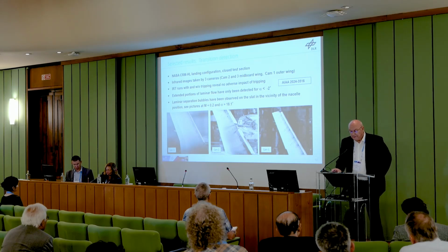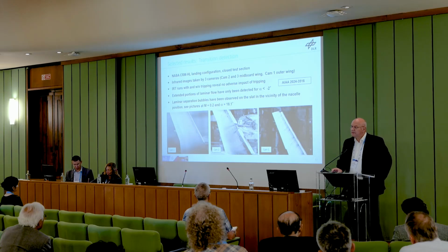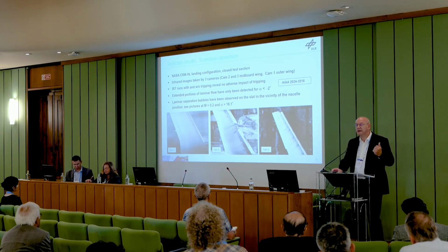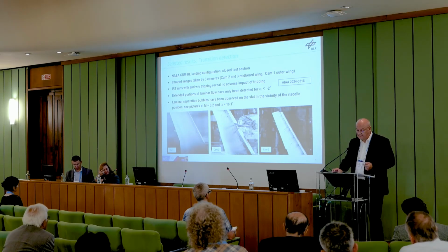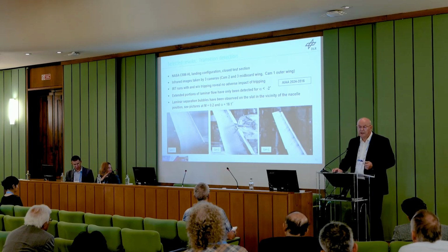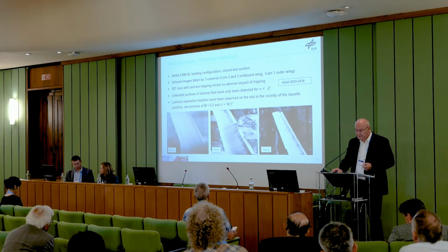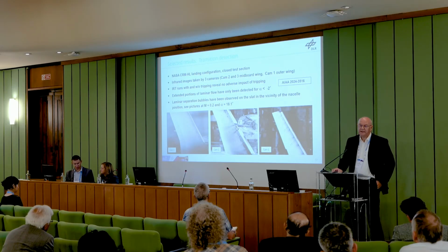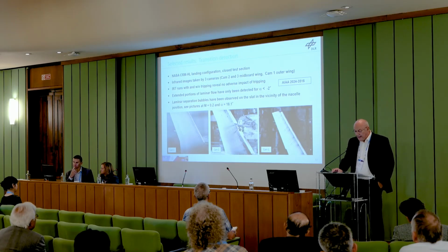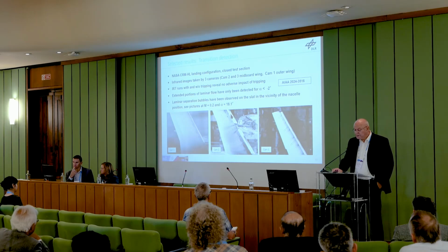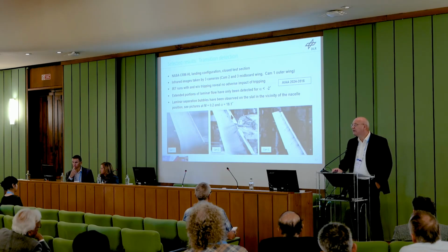And it was at the same time a check for the wing transition dotting. We had dots at the wing roots, behind the nacelle, here at the fixed wing leading edge, at the slat cutout, and at the outer wing, and on the nacelle and the fuselage nose. So these have been taken away, and then put on, and measurements have been taken. And at the same time, we also did a checkout between track 13 and 14.